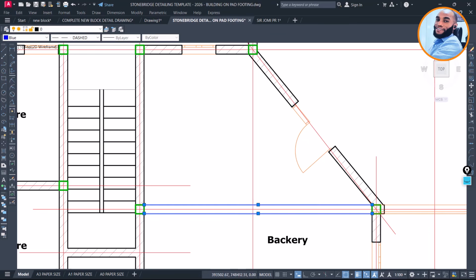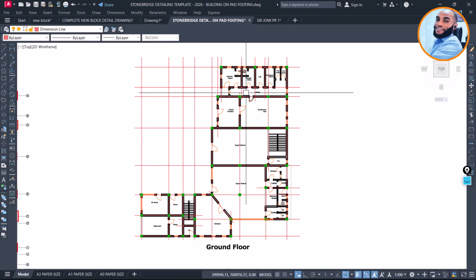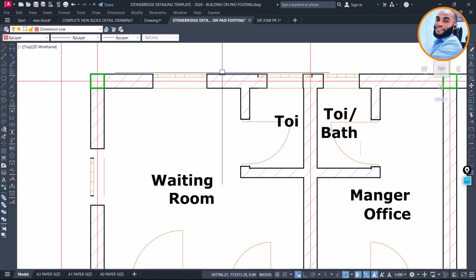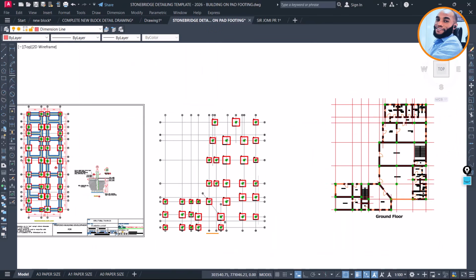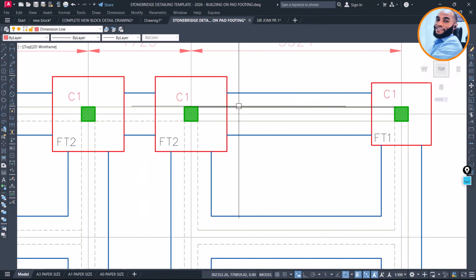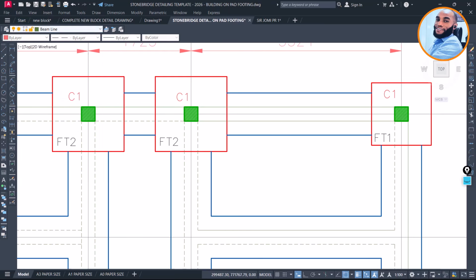That is fine. So knowing this, the next thing I'll do is to now do what? Copy my wall lines to import there. And how do I do that? Just to be fast, I will come here and look at the layer that was used on this place. I'll touch here. You can see the layer is beam line. So I'll come now and make sure I type beam line and make sure that the active layer is called beam line, and this place must be beam line and not by layer.